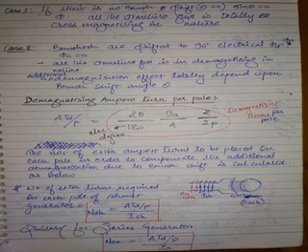So we will be discussing armature reaction causes for 2 poles for understanding, and it is true for any number of poles. Same thing happens. Now the concept is under a pole always 180 electrical degrees. In this 180 electrical degrees, how much theta is doing demagnetization? Theta is also in electrical degrees only. Everything is in electrical degrees. Out of 180 electrical degrees under a pole, 2 theta region is offering demagnetization. Yes or no? Under this pole of 180 electrical degrees, again 2 theta region is offering demagnetization.